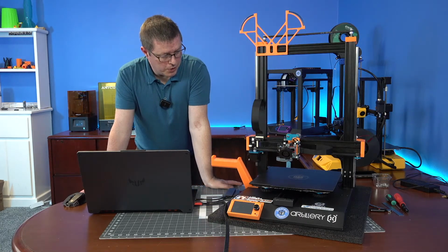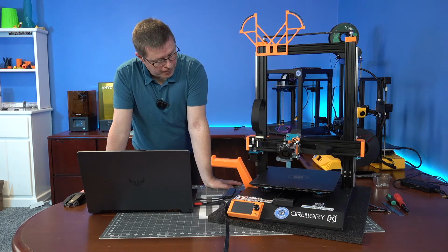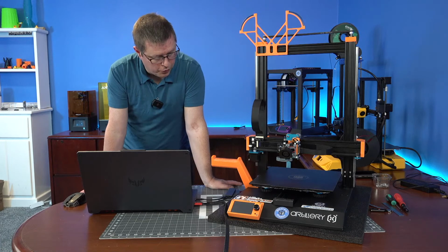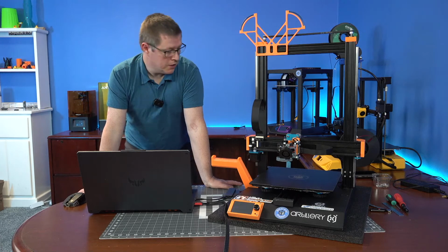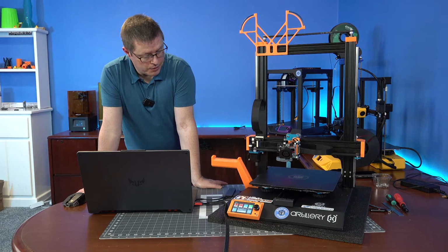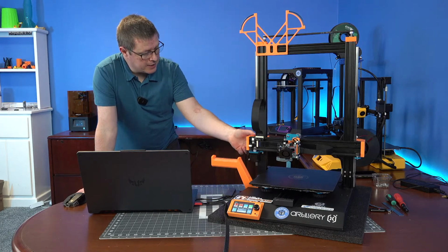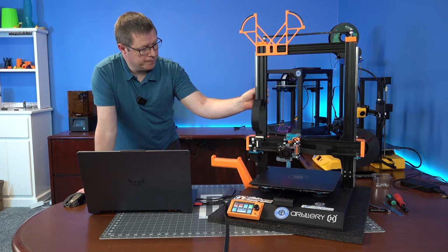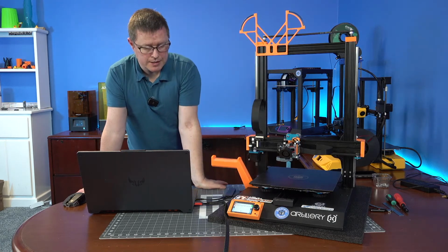It originally came with a direct drive Titan clone extruder, and I have put an SKR 1.4 Turbo with the BigTreeTech screen, the TFT 35 V3. Turn that on, get it updating. Switched it out to a Hemera with a Volcano hot end, installed a BLTouch, switched over the Z-axis motion system to linear rails and 1204 ball screws to give a little bit more resolution in the Z-axis.